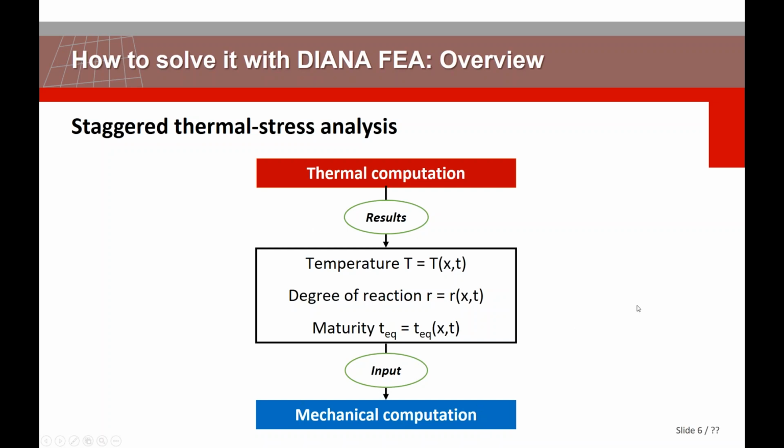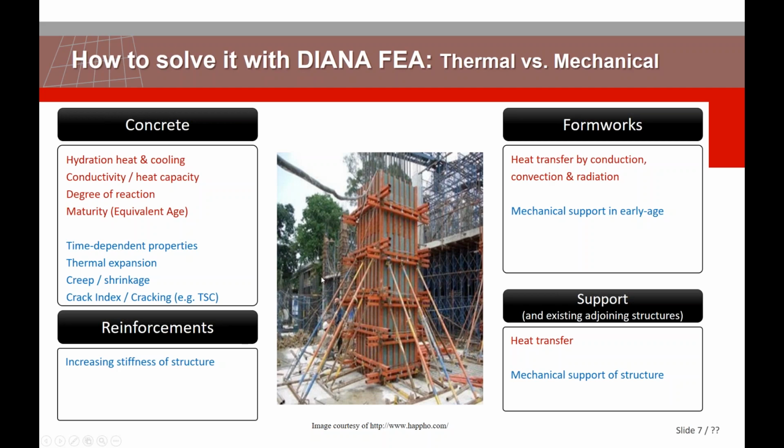This is the concept, and if I go a little bit further, you have concrete, reinforcement, and formwork and support. Heat of hydration, cooling, conductivity, heat capacity, degree of reaction, and maturity are thermal aspects, while the time-dependent properties, expansion, creep, and shrinkage, are mechanical aspects.